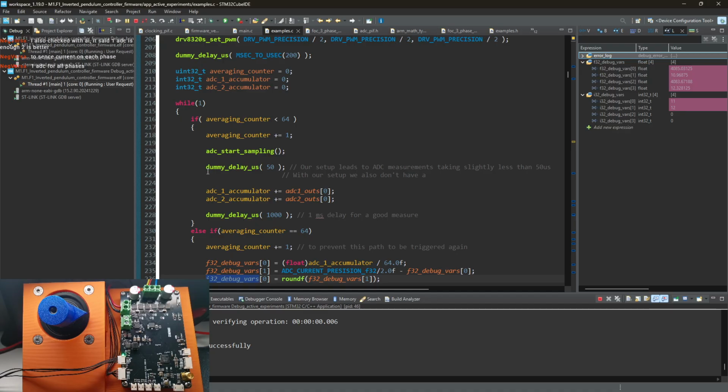When ADC for all phases? Oh, no, I hate it. I actually hate it. I think AI is wrong. It may be enough for a low-end motor controller, but there are very, very good reasons to use 1 ADC separately for each phase.